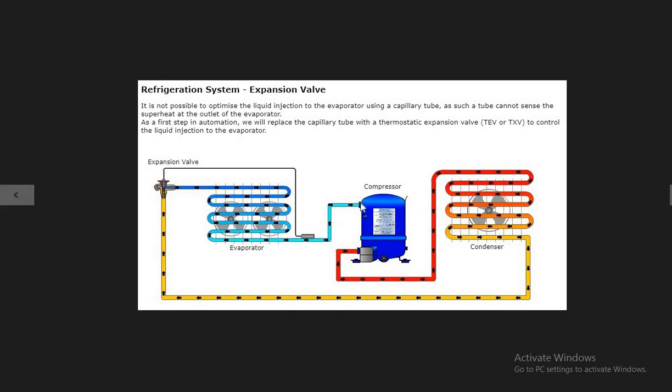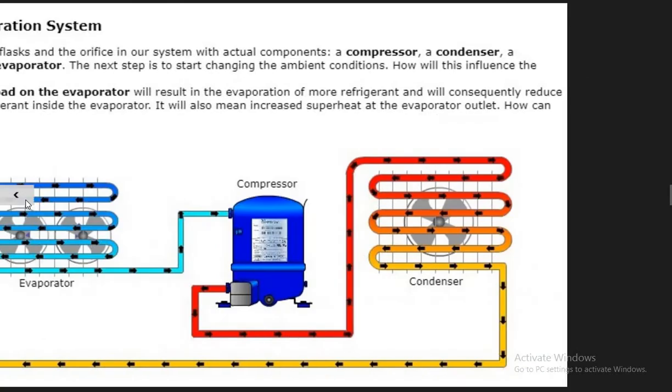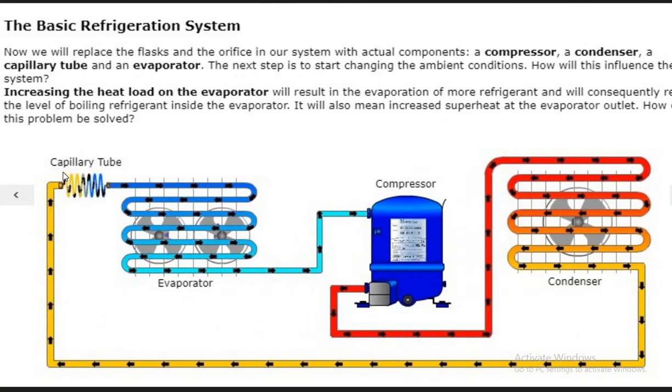And if the load on the compressor is lower, then it is not going to take enough current supply, and with that you are saving some electricity. In turn, you are saving some money. This is an intelligent way of doing it. However, the capillary tube is a fixed way. There is no fluctuation. You cannot bring about any change in your system, and so the current required will be the same. It will be steady. And due to these differences,